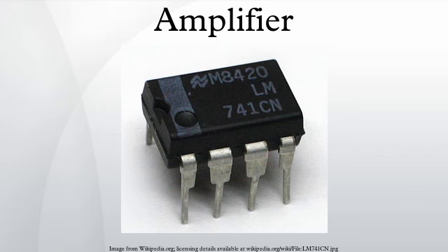Class A. Amplifying devices operating in Class A conduct over the entire range of the input cycle. A Class A amplifier is distinguished by the output stage devices being biased for Class A operation. Subclass A2 is sometimes used to refer to vacuum tube Class A stages where the grid is allowed to be driven slightly positive on signal peaks, resulting in slightly more power than normal Class A, but this incurs a higher distortion level.